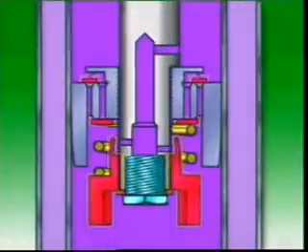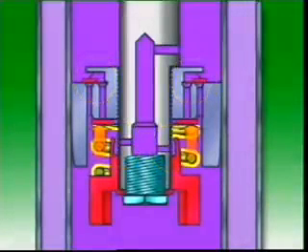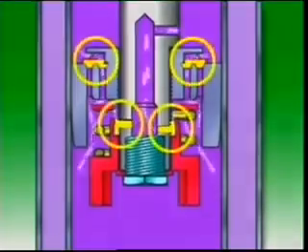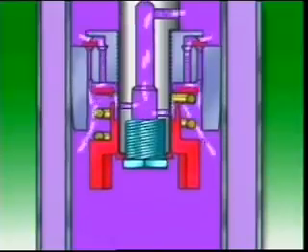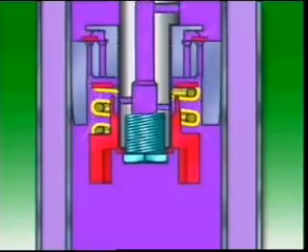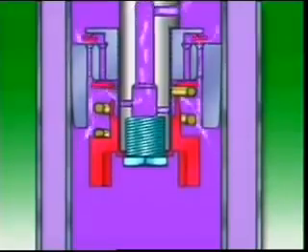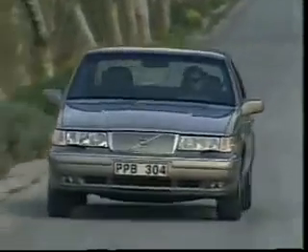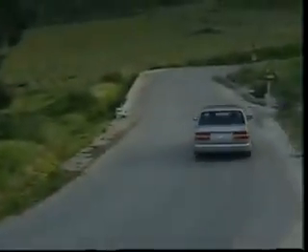The position of the valves in the piston can then be changed to vary the number of restrictions the oil has to pass through and to vary the force needed to open the valves. In this position, all of the orifices are open, and a small dampening effect is applied to the oil. The spring force applied to the valve is also reduced to allow the valve to open more easily. This means the oil can flow through the valves more easily, which gives a softer ride, but can also allow more rolling and pitching of the body of the vehicle.